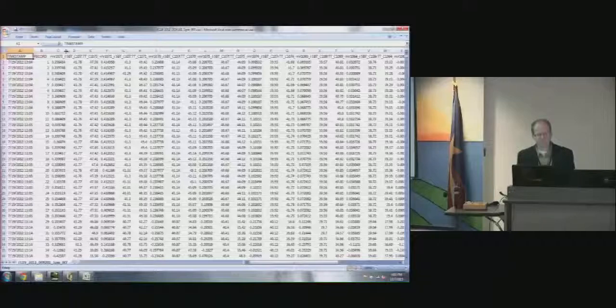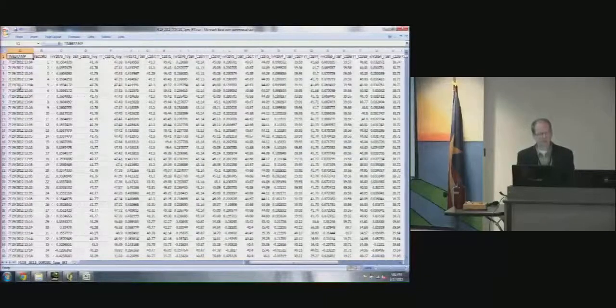What we're showing here is in the first column a timestamp. I think this second column is just a record counter. The key pieces of information are here. In the third, fourth, and fifth columns, we have data associated with one IRT sensor. In the first one there, in column C, is a millivolt output. This would be whatever analog millivolt reading that sensor was outputting at that time.